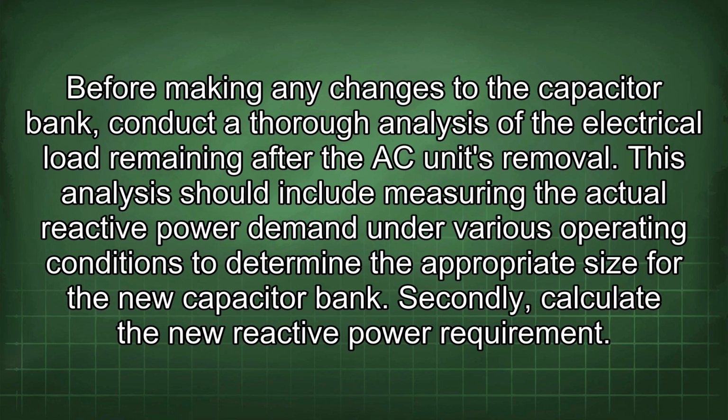Before making any changes to the capacitor bank, conduct a thorough analysis of the electrical load remaining after the AC unit's removal. This analysis should include measuring the actual reactive power demand under various operating conditions to determine the appropriate size for the new capacitor bank.